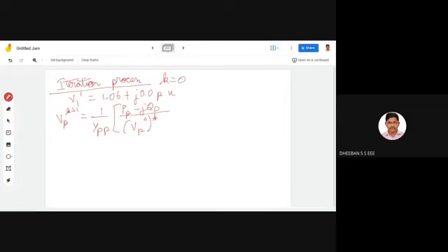And over here, minus summation q equal to 1 to p-1, ypq remains the same, Vq^(k+1). After this, minus summation q equal to p+1, extending up to n, ypq and this will be Vq^k. Okay, so we have written the voltage equation.